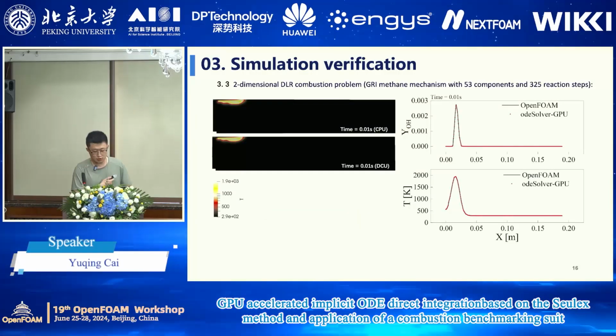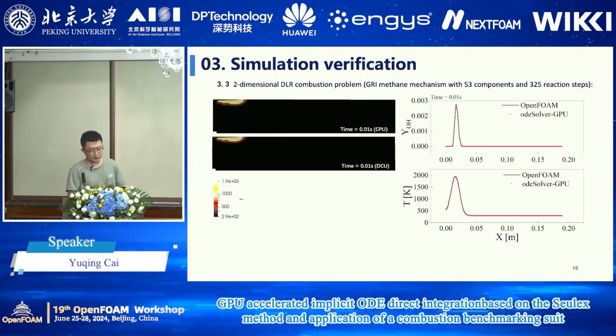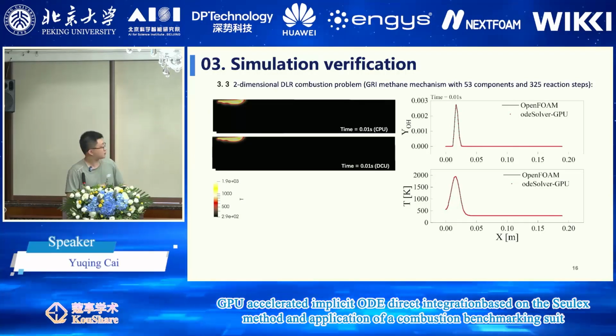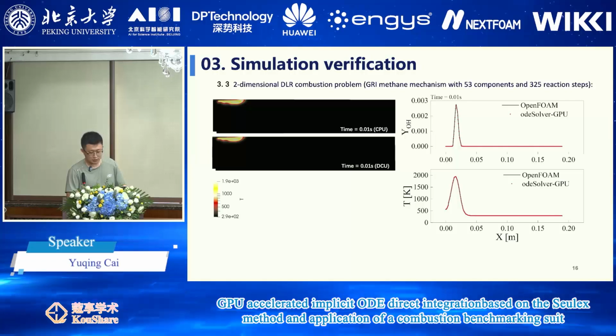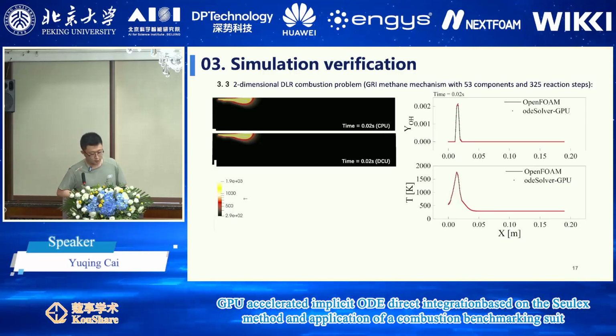This page shows a two-dimensional verification. The DLR test case is a standard jet combustion tutorial in OpenFOAM, and we can see the calculation results of OpenCC and OpenFOAM match very well. And at the next time step, the calculation results are also consistent.